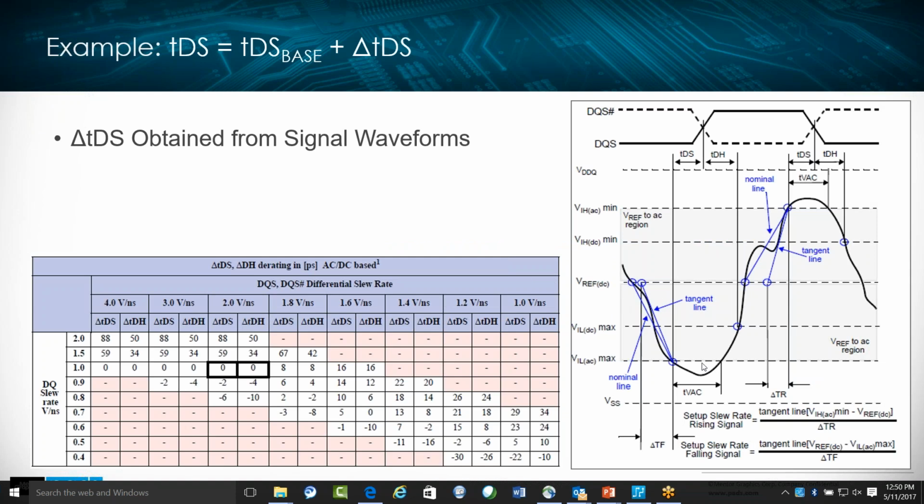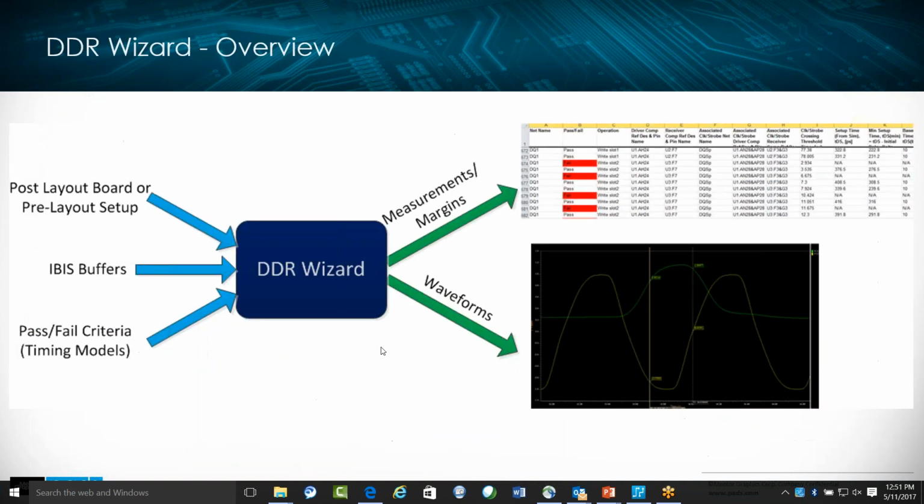So here's an example of actually looking at a waveform shape on the right-hand side. And you can see as the signal is going up, it doesn't always continue in the same direction. And that could be an example of what we just talked about. What if the slew rate's too slow? Do we really have to wait for this to get all the way up there before the data is valid and we can clock it? And the answer is, no, we don't have to wait. So we look for these delta T times. So this is some of the topics that you want to understand as you look at the double data rate memory interface. That's called slew derating.